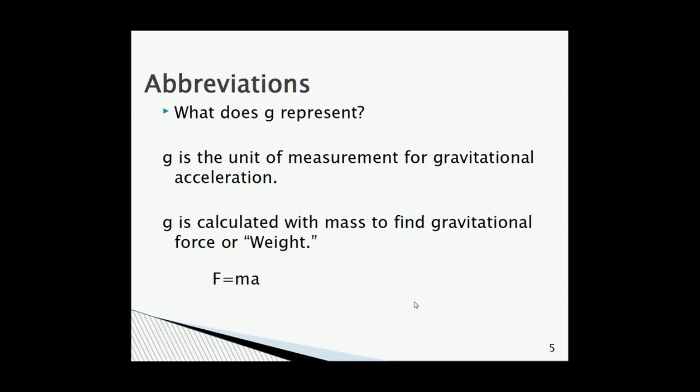You will then sum up those masses and multiply it with your given test profile's acceleration value. And this will determine whether or not your shaker has the force capacity to perform a given vibration test.